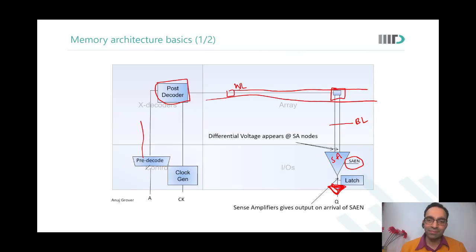What comes to my mind is I think it should carry the whole architecture, because if we just add the array, then we need to have the IO ports and all also in the phone. Yeah. So in terms of SDRAM or something, you will see there are only 8 data bits available on the chip. But your DRAM array would have how many columns? Thousands of columns. How will you access them? So you have to have all this control circuitry, everything in there. That is what a memory is. Otherwise, you would call it a memory array.